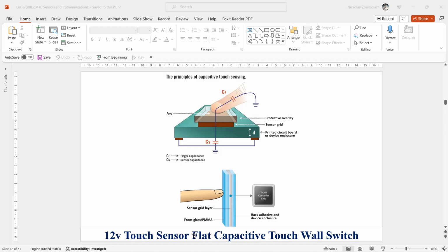A single capacitance in the initial position may produce a considerable output signal which cannot be amplified much more, unless it is first compensated by an equal but opposite offset signal. However, compensation by an equally shaped sensor is more stable than compensation in the electrical domain.